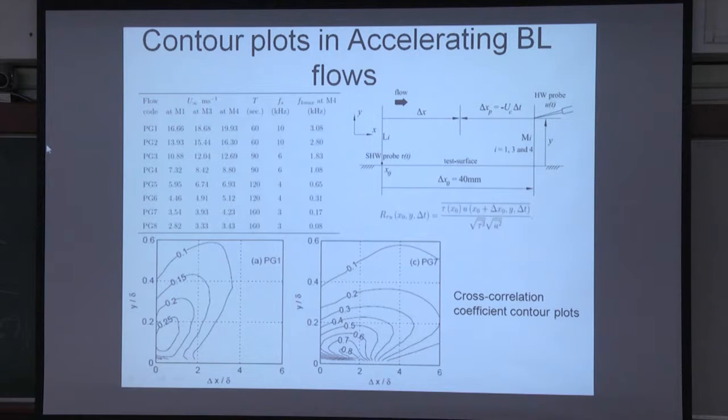For sampling theorem demands, if you are interested in capturing a particular frequency, you have to sample at least 2 times that. But don't do just 2. Maybe do 3 or 4. 4 should be okay, generally speaking. So if you want to capture the Kolmogorov scale, clearly you can work out different ways of doing that. None the most obvious, but let's look at the Kolmogorov scale here, typical numbers you can see here.